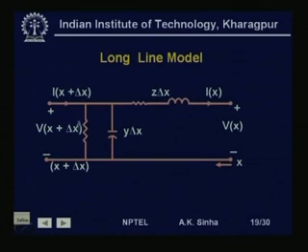So, in this way we had seen how we can model the transmission line for short lengths and medium lengths. But when transmission line lengths are very long, which is the case in extra high voltage lines or some of the lines which are connecting the remote power generating sources such as hydel plants to the load center, then in that case it is no longer possible to use a lumped parameter model, and we will have to use the distributed parameter model or the more accurate model. Otherwise, the errors which will come because of using the lumped parameter model may not justify the simplification that we have used. So, here again we come back to the distributed parameter model.